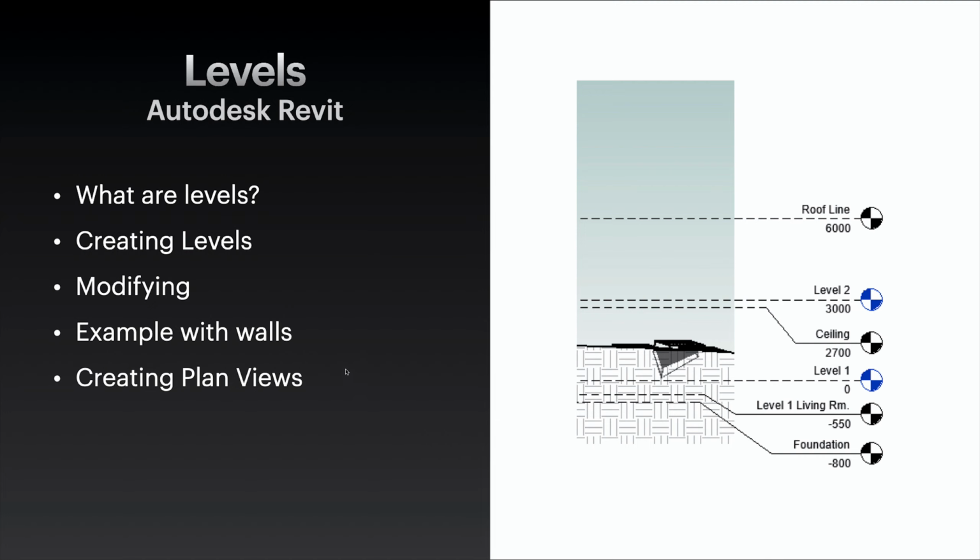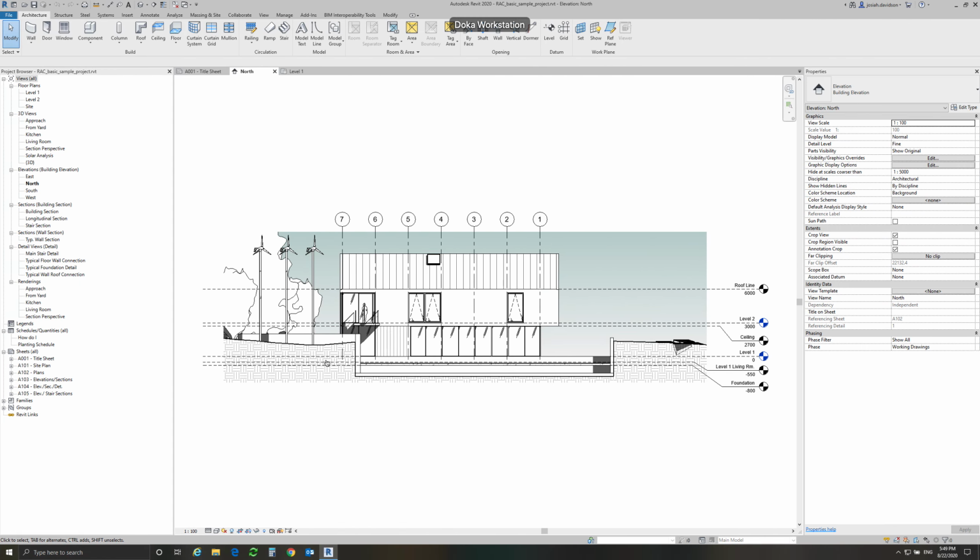In this video, we're going to talk about levels. We're going to talk about what they are, how to create them, how to modify them, give you a quick example of how they relate to walls in the concept of your entire Revit project, as well as how to create plan views from these levels. So let's begin.